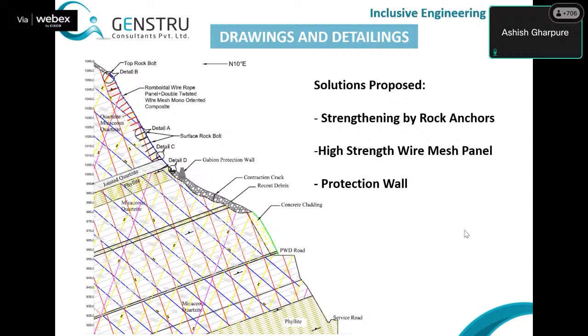Once you are done with your design, then you have to go to the drawing board, sketch it out, and plot all joints and how you are going to give the details, whether it's a protection wall, where the location should be, and how you will treat which zone. Some are with anchors, some with walls, some with pitching. So all has to be detailed in the sketch. Next.